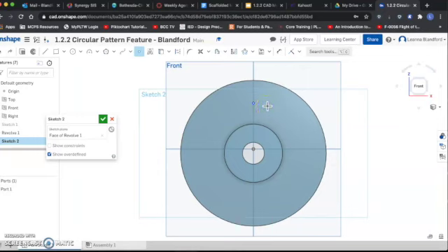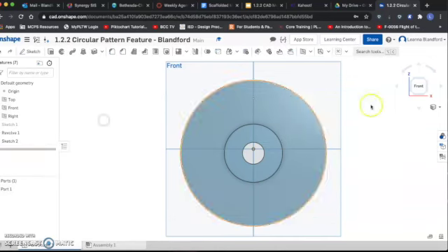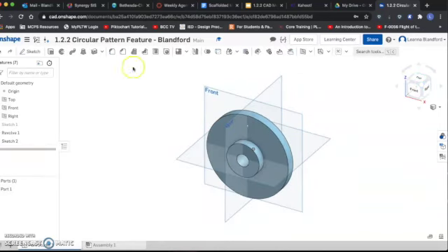Now you'll notice in the drawing it's indicating that we have 1.65 from the origin. Now, my drawing is not completely on the origin, so I am going to guess that it's probably closer to 1.5. So I'm going to dimension from here to the top edge of the circle as 1.5. And that looks pretty consistent with what I'm seeing inside of the pictures on slide 23.